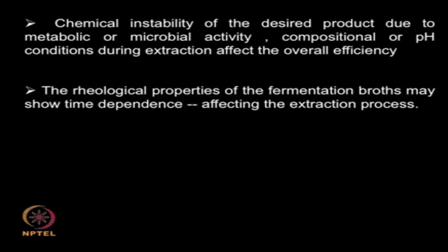If you take a fermentation broth and it contains cell mass, dead cell debris and so on, it will be highly viscous, and we need to now mix your solvent with such a highly viscous fermentation broth. So the rheological properties will have a bearing on the extraction process. So you need to keep those points also in your mind.